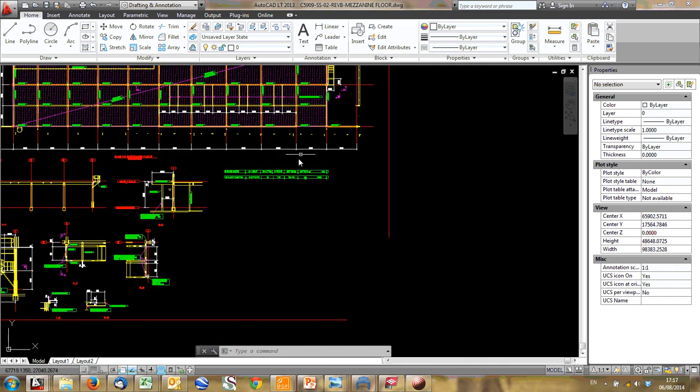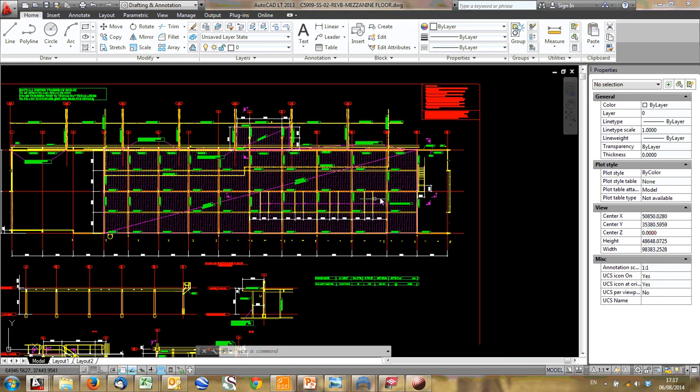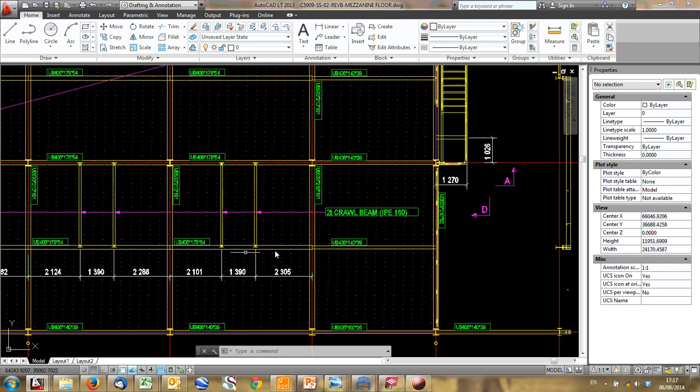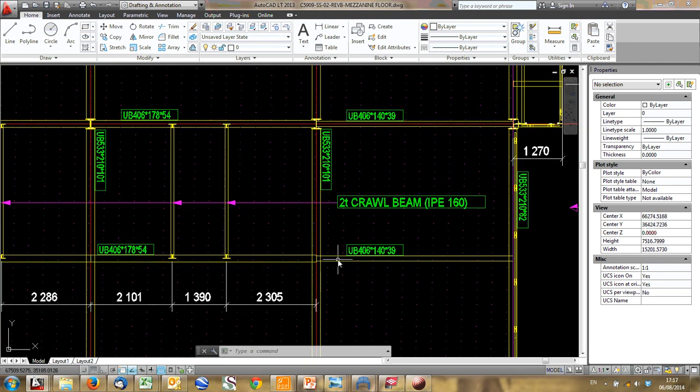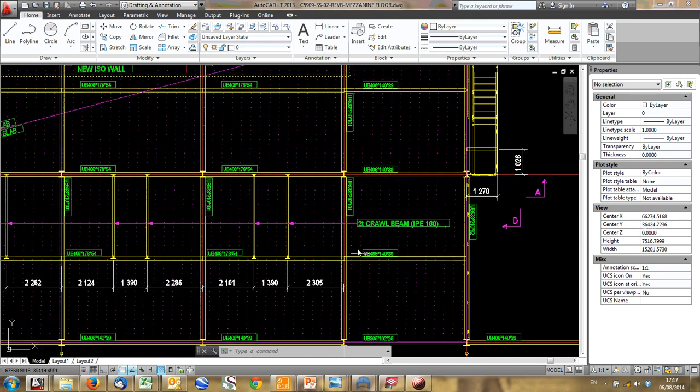You don't connect your flanges from one to another. You simply connect the webs together. You have a cleat or a thin plate or something, and you connect this beam to this beam. So you don't pass moment from this one here to this one here. You can actually isolate, so you know the force stays here and you know the force stays here.